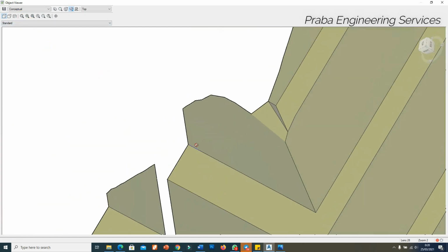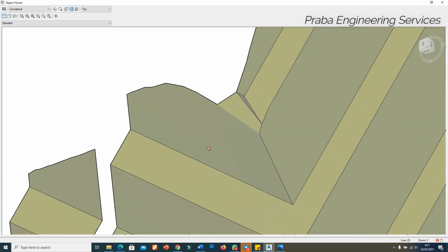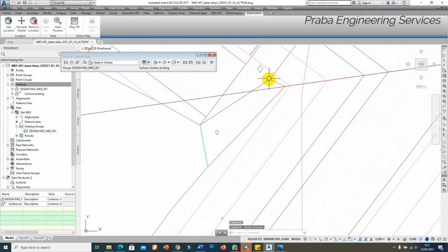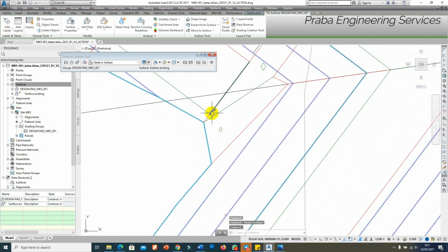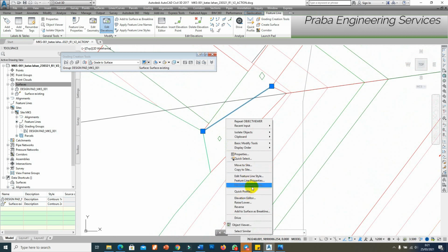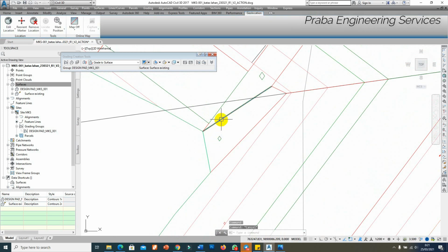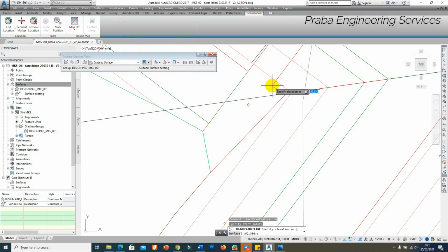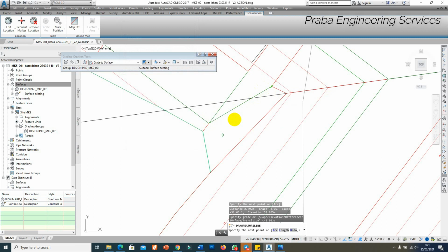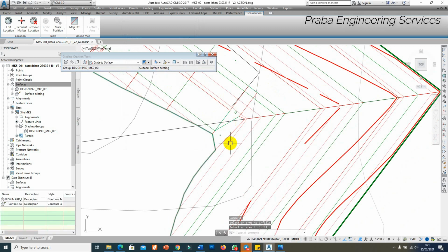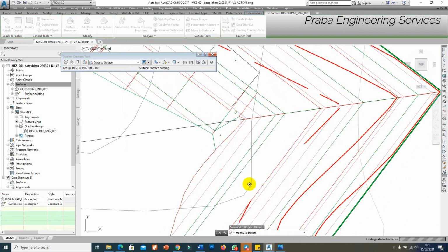And you can modify from here to here to here. Okay. This one from here. Okay, so I want to delete this feature line. Erase, remove, or delete the feature line. So the feature line I want to put from here, the lowest one, to the corner. Enter to the corner. Enter. Okay, check create infill. Then see what's going on in here in the corner.